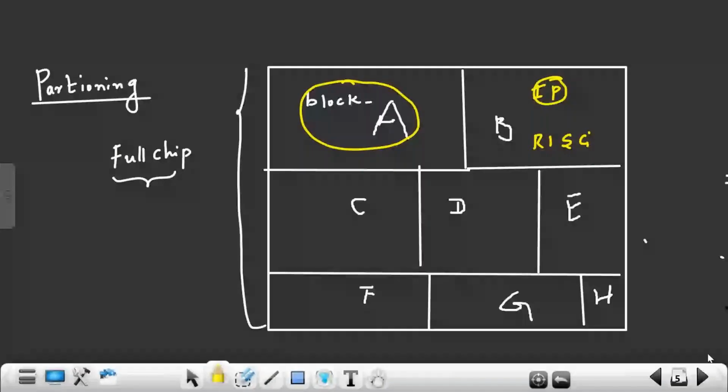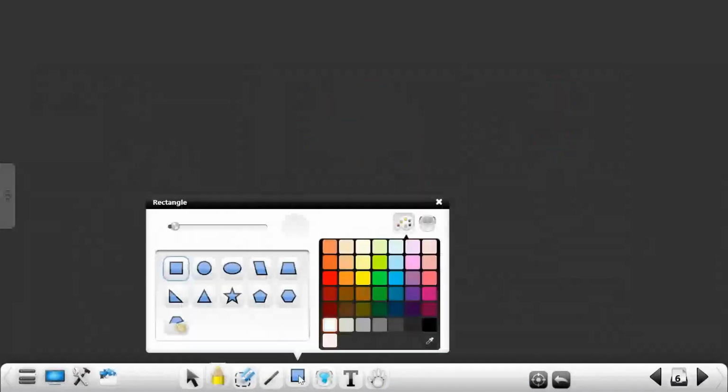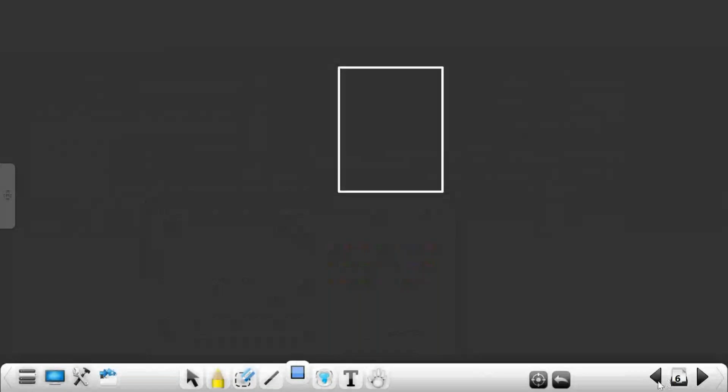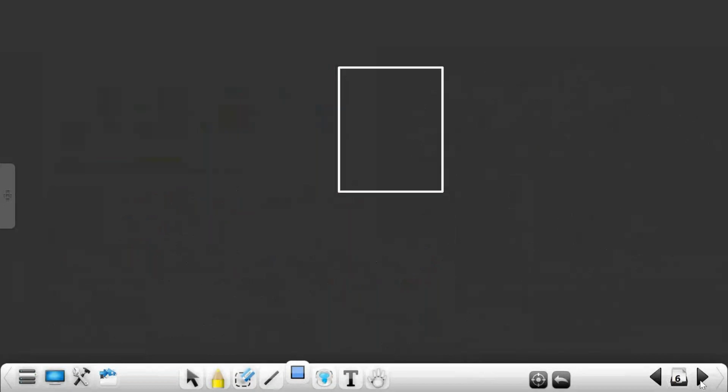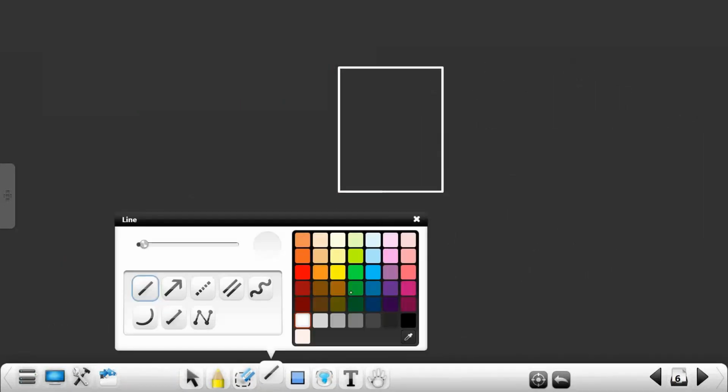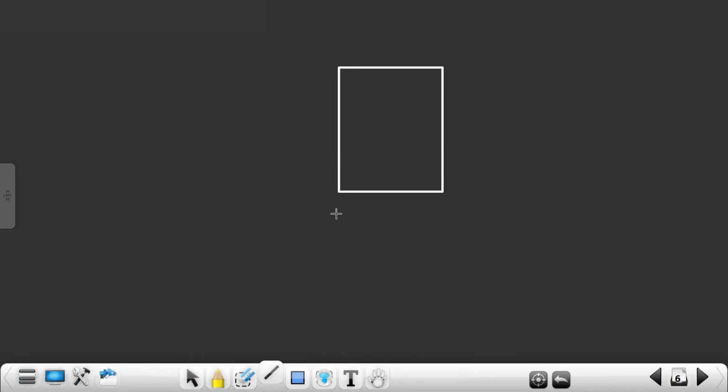For that netlist, what I do is estimate how much area I need to place all the cells. See, if you take the layout of a cell, right? What is the layout of a cell? I have already shown you. This is called the layout of a cell. For this layout of a cell, we know what the width is. This width is mentioned in the .lib file.